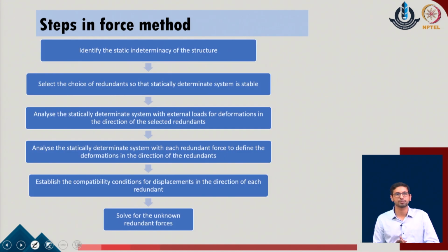So, as we define the basic steps in the given analysis, we understand that first we identify the degree of static indeterminacy for the given problem. If the system has n degrees of static indeterminacy, then from the original system we remove n reactions. We have seen right now only the external reactions being removed because it was a simple beam problem. In the cases of trusses or certain members where internal indeterminacy is also available, we need to remove the internal members or the internal unknowns of the given problem as well.